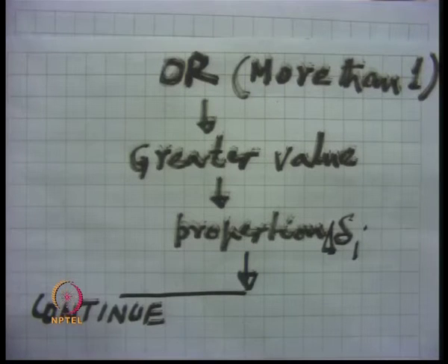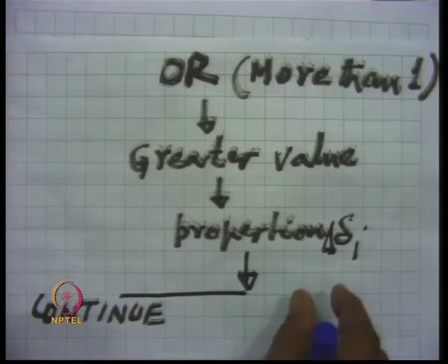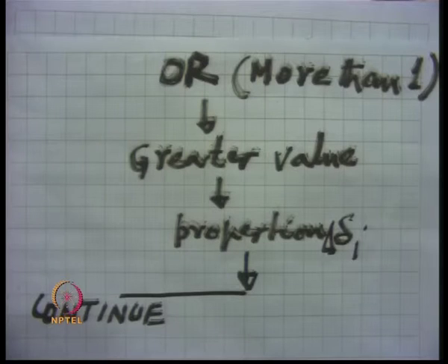In that case, the incremental displacement becomes non-uniform, but that does not affect the solution, and one can continue in this particular fashion. That is, we can go for the next increment of displacement with a plastic hinge forming at one cross section only at a time.